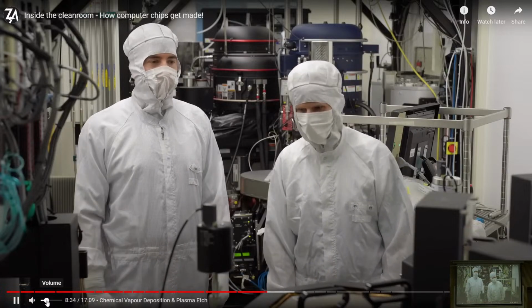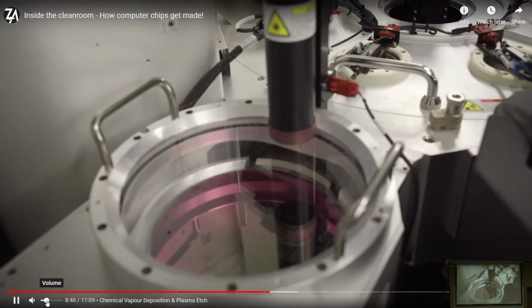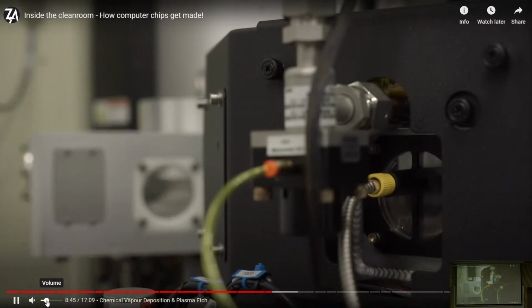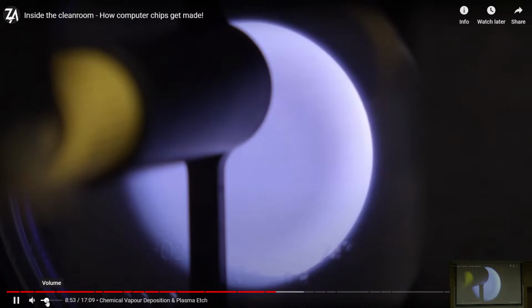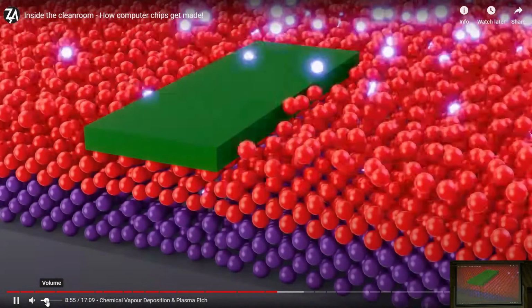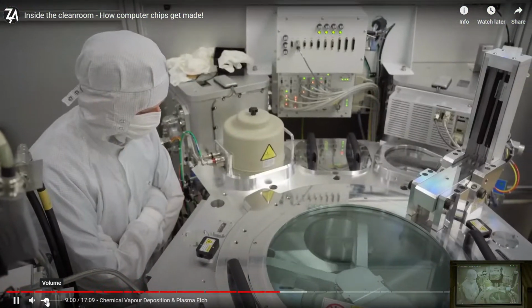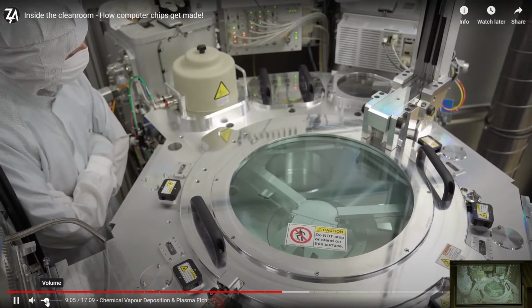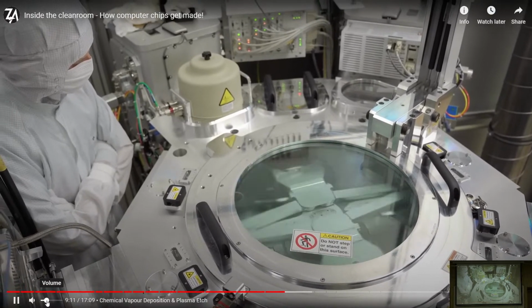So here we are in the maintenance area of the clean room. In these kinds of tools, we etch away material, as the name says, and we do this by creating a plasma above the wafer. We have reactive gases above the wafer. They get ionized in a plasma, and the way it's constructed is such that the plasma can react with the material that we want to etch away. And the special thing about plasma etching is that we can actually control the geometry of the structure, for example the sidewall angle.